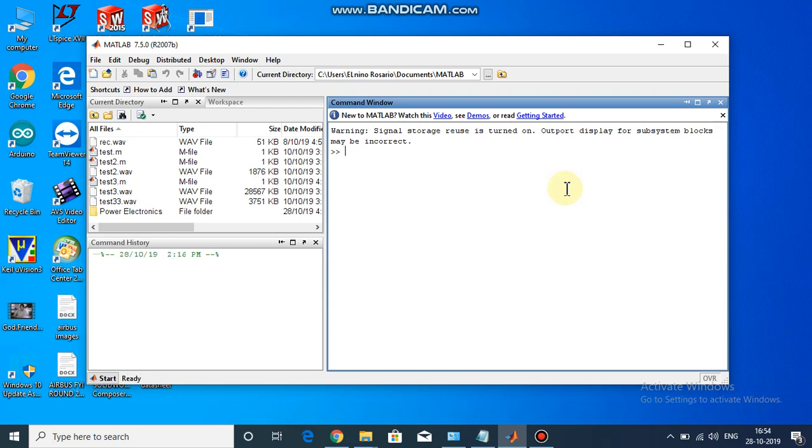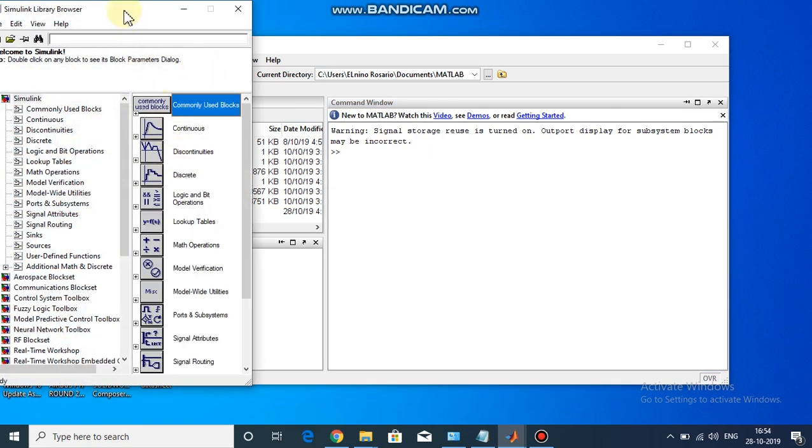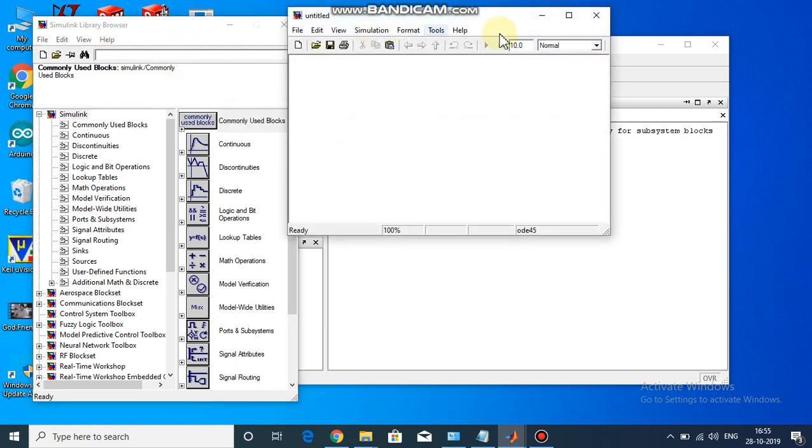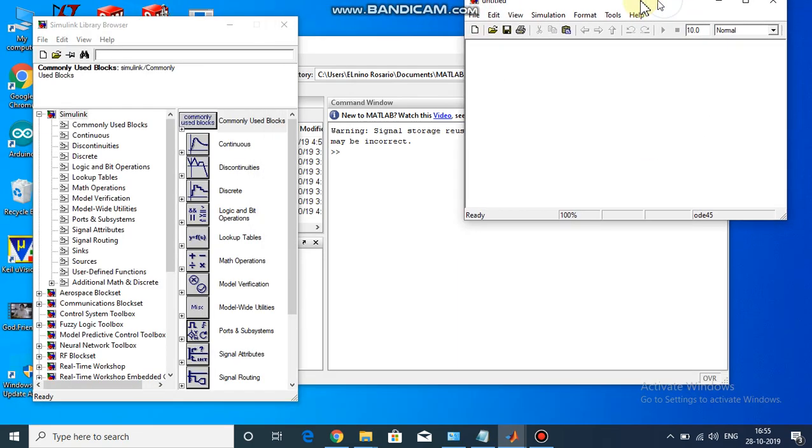Hello friends, welcome to my channel and let's start with MATLAB Simulink video for today, that is Class C commutation circuit in power electronics. Now here we will start our Simulink from this icon above, and now you can see the Simulink library browser. You just have to press Ctrl N or just go to File, New, Model, and this is our Simulink model that we'll be having throughout.